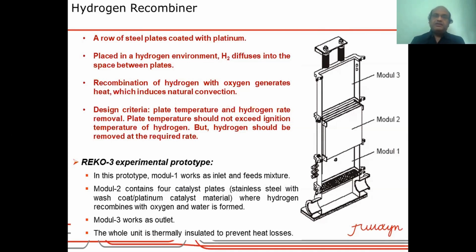But there is another thing at the same time: the gaps between the plates. If you look at the gaps between the plates, they cannot be too wide, because if it's too wide, then the reaction rate, the removal rate, will be low. If it is too narrow, then the frictional losses will be high, and again there will be a decrease in the removal rate. So the design of this device, even though it looks very simple, is a bit complicated. You have to consider a lot of factors.